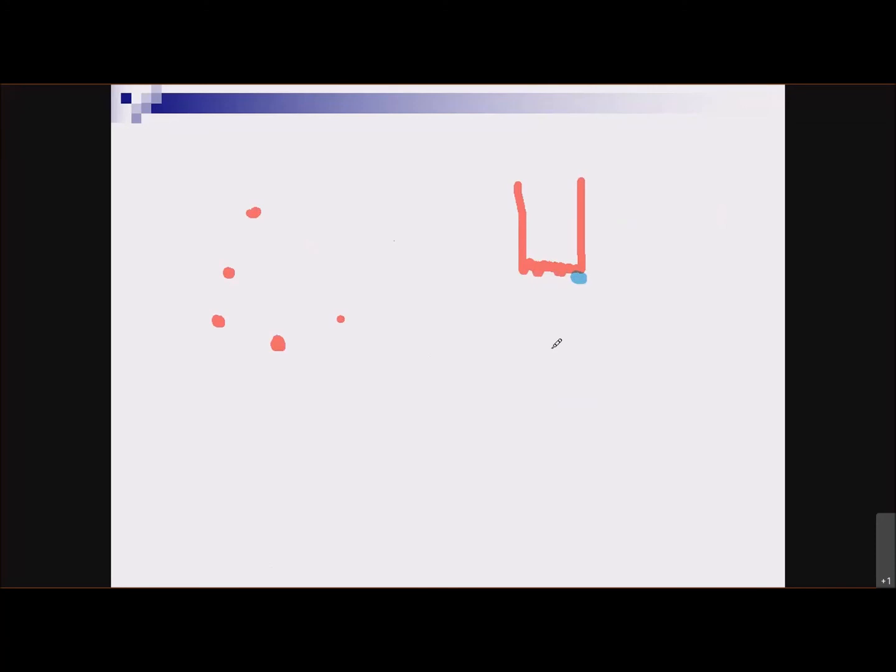So if there's a small amount of air flowing in, and this is not by volume, this is by mass, so density matters, there's a small number of molecules of air hitting that sensor and taking heat away. So it does not take a whole lot of current.